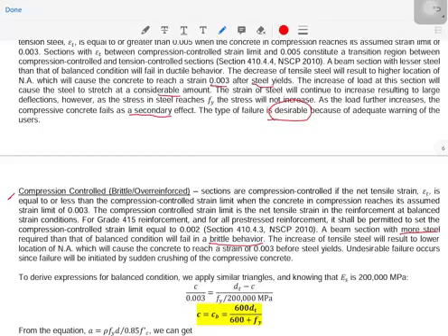So para mapulbo siya. So the increase of tensile steel will result in a lower location of the neutral axis, that will cause the concrete to reach a strain of 0.003 before steel yields. Again, this is undesirable. Failure occurs since failure will be initiated by sudden crushing of the compressive concrete.